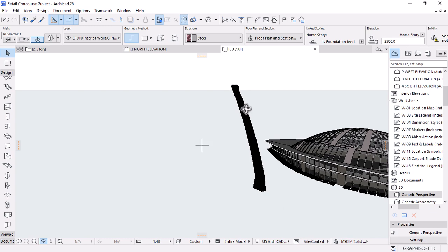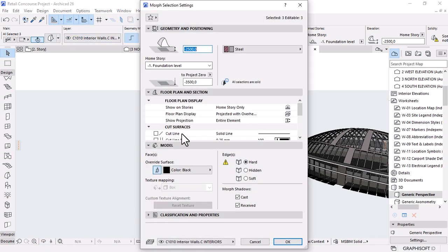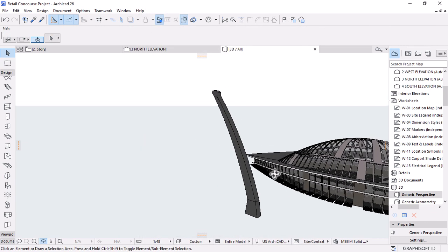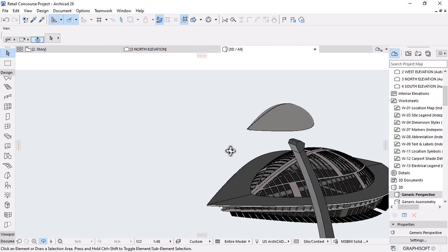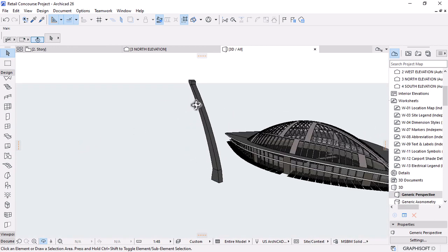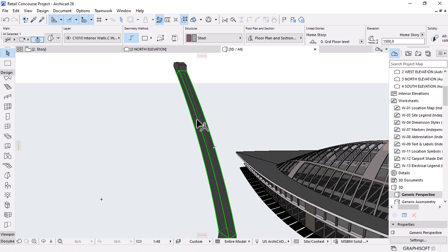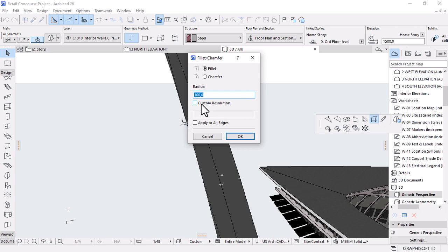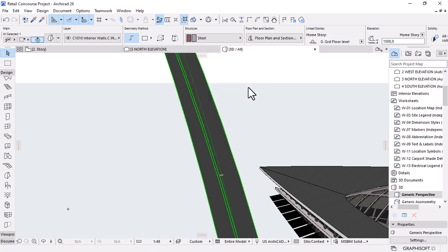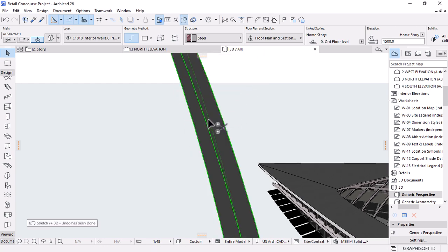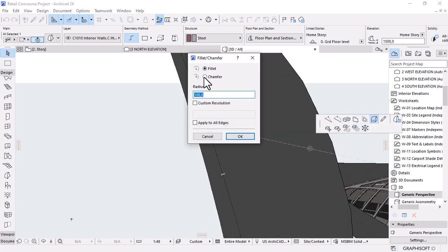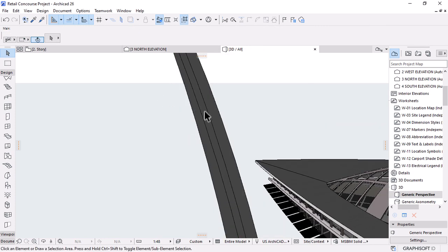Yes. Let me get rid of this dark color because it doesn't do justice. I'll overwrite the surface. Let's see. Perfect. And then what we need to do is to play around and fillet the edges of that. I would use 100. Now, nope. I don't want to round edges, I want to chamfer. So I'll use 500. There we go.